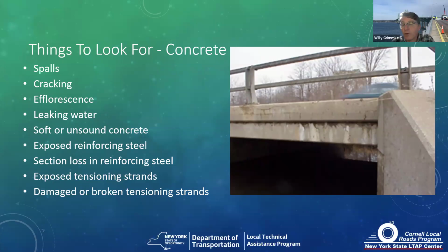Do you have unsound concrete or soft concrete? And you can determine that by banging on it with a hammer or piece of rebar, and it will definitely sound different. Is your rebar exposed? If it's pre-stressed or post-tension, do you have exposed tensioning strands? And are they corroded or broken?